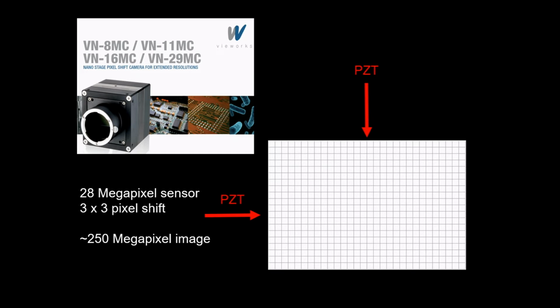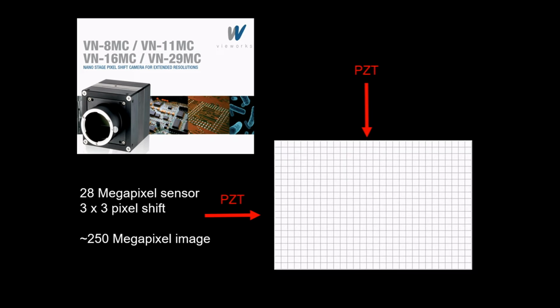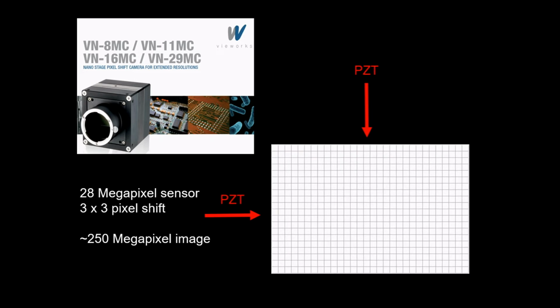So what we eventually found, thanks to our friends at Teledyne, who gave us a call and said this might work for you, even though they weren't selling it, so kudos to them, is a CCD sensor, 28 megapixels only, but it's located in 2 orthogonal piezoelectric transducers. And when we apply a voltage to these, rather than moving the sensor by, for example, a full sensor width, we move it by a fraction of a pixel only. So we move it through 9 by 9 positions.